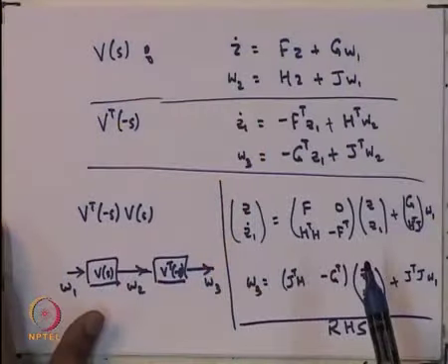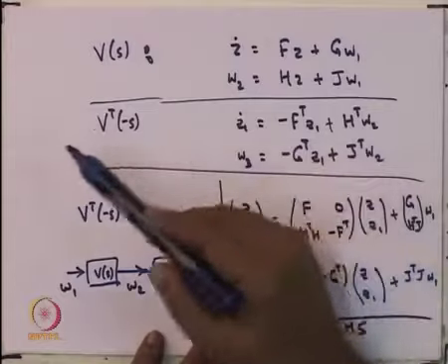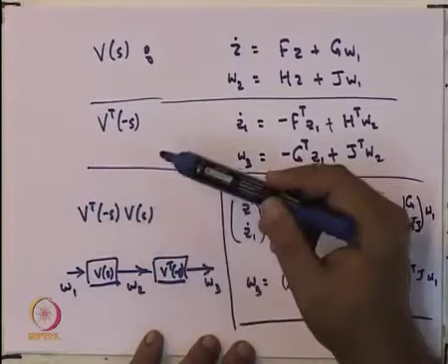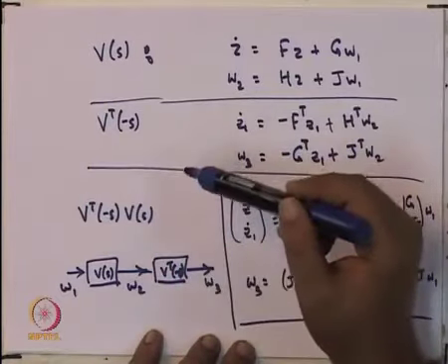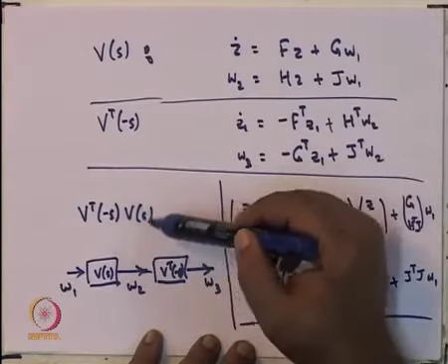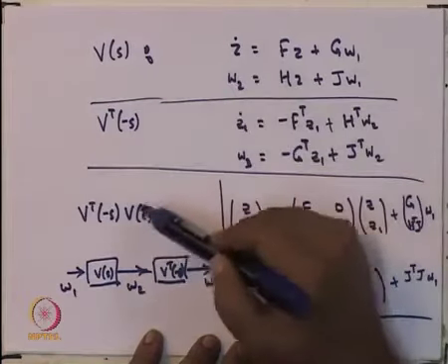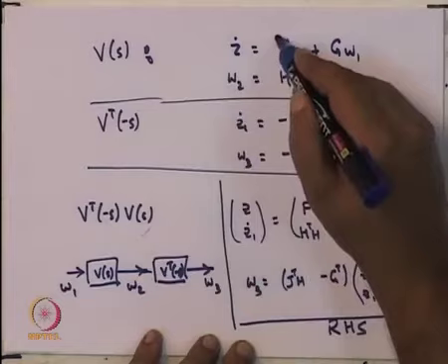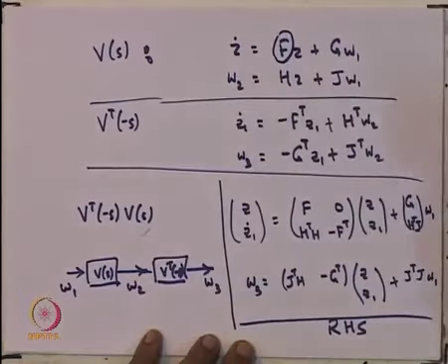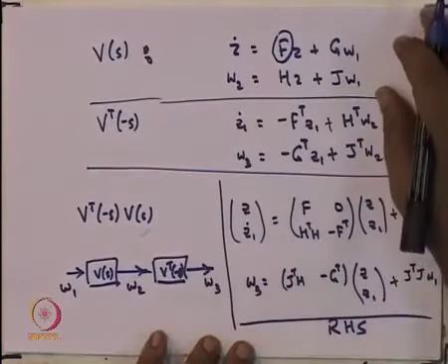And okay, so one other thing that I wanted to mention is that from the spectral factorization theorem, we get that G transpose S plus G S plus G transpose minus S is equal to this product V transpose minus S V S, and we can always take this V S to be Hurwitz, and if V S is Hurwitz, this matrix F is a Hurwitz matrix. So, please remember that this matrix F is a Hurwitz matrix.